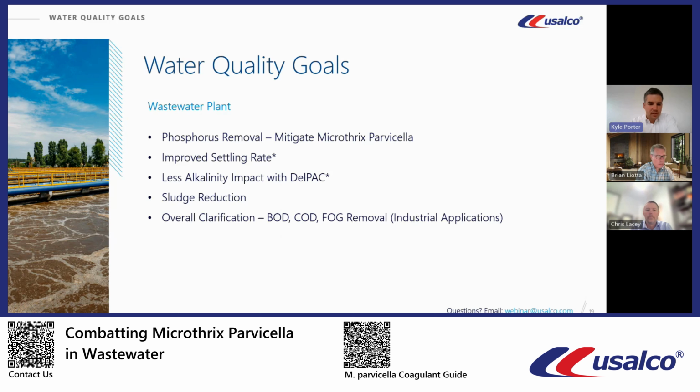And then lastly here, with your water quality goals, of course, you're looking to get better settling. The whole idea is that it allows you to run as high of a mixed liquor as possible so you can get optimal performance for your BNR treatment. And of course, having better BNR will let you get better nitrification and better phosphorus removal.